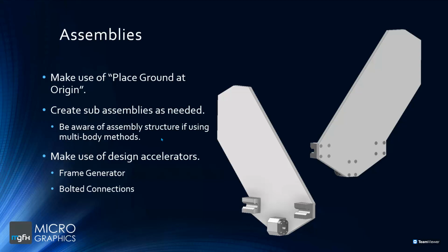Typically, if you want to create any sub-assemblies, you would need to push those multi-body parts out separate as sub-assemblies in those groups, should I say, and then assemble them all together. And I'll run through an example of that in the design here as well.